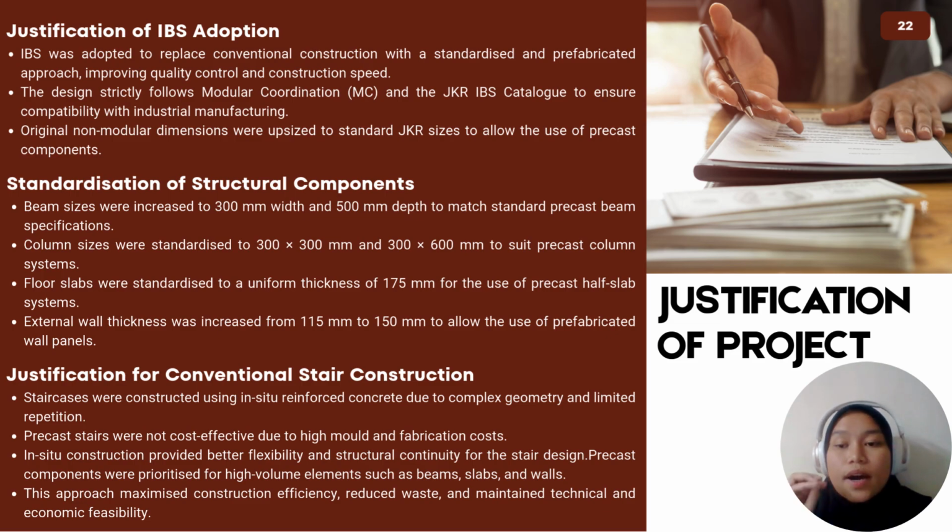So we go to the overall outcome. You see, the precast used for high volume components reduces waste and construction time, and maintains technical and economical feasibility. By focusing IBS on high volume components such as beam, slab, and wall, this project achieves high efficiency without incurring unnecessary customization costs. So that's all for me.